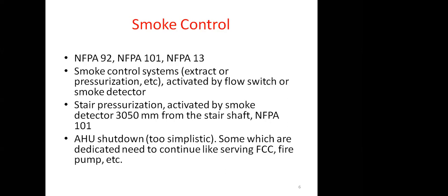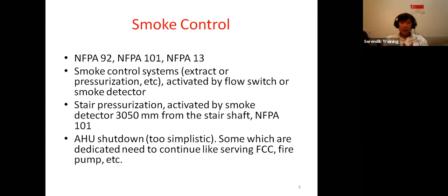Yes. Okay, cool. The next major system that we also come across is the smoke control system. This smoke control system requires in-depth understanding about how it is being activated. Once again, it should not be a case where, when there's a fire detection somewhere in the building, all smoke control systems are activated simultaneously. You have the fans working, but you will not have the performance achieved.